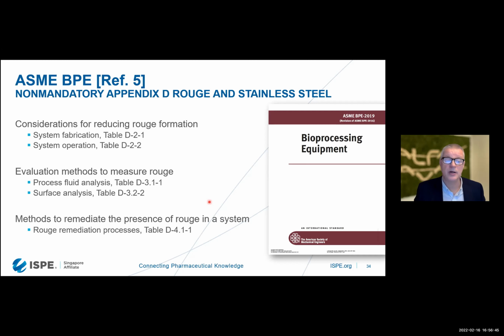And it's also about evaluation methods to measure the rouge, because now more and more measurement systems are coming to measure the rouge, either inline, where you're measuring the water, or an invasive method where you actually have to drain the system and measure on the actual surface.